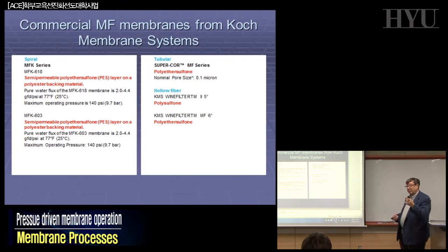If you want to avoid concentration polarization, instead of working at a very high linear velocity for inducing turbulence, you can induce local turbulence by increasing the roughness of the surface. Instead of having a very smooth surface, you can have a very rough one. In some cases, you can create small protuberances on the membrane surface at molecular level. That means a few 10, 20, 50 angstroms of thickness, and this can operate as a local turbulence promoter, and minimize concentration polarization, fouling formation, etc. So all these parameters can be checked.